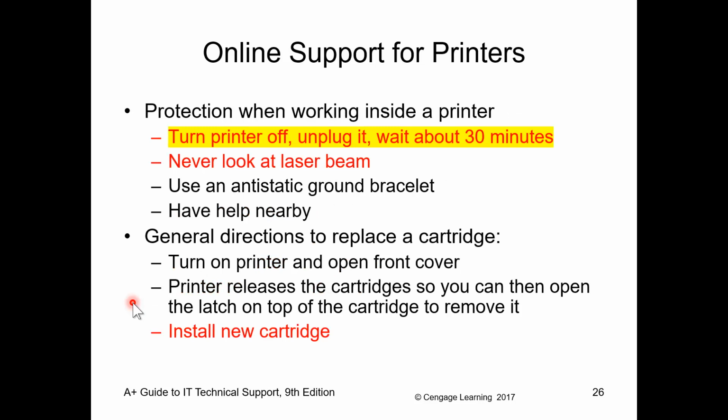Working inside of the printer involves strong electric charges. It has capacitors that hold power even when the printer's turned off. So you want to turn it off and unplug it. What I would then do, once it's unplugged, is turn the switch back on and leave it for a while to make sure those capacitors are drained. Of course, it's got a laser. You don't want a laser shining in your eye. It could hurt your eyes, so you don't want to be inside the printer when it's turned on. Use your anti-static protection.